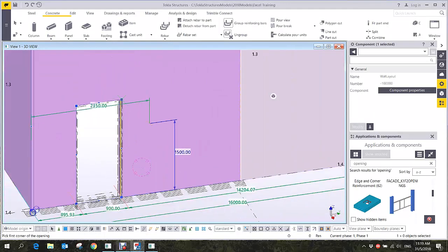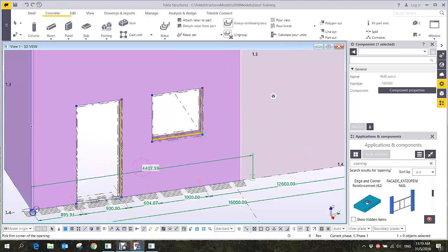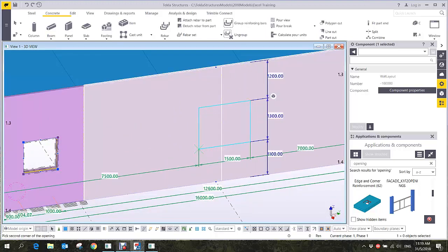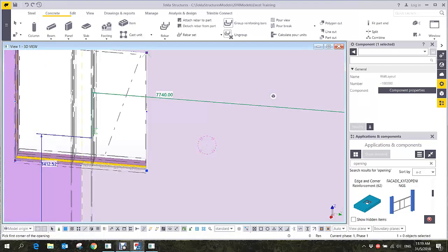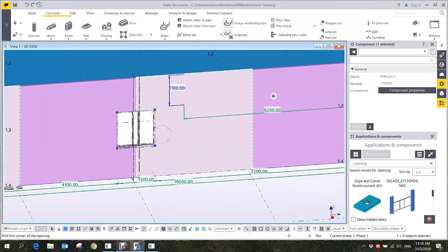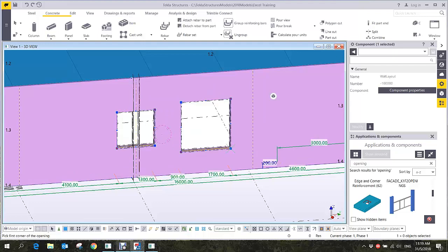So if I want to have a window opening here, so from here, then that is the size, 1000 by 1000, and then I have the opening. So let's say, for example, I have the opening from here, 2 walls. Remember, that one is the connection of the wall, right? So I can have the opening in the middle of the 2 walls. Okay, again, click, and then here you have this opening. So this is the direct modification.